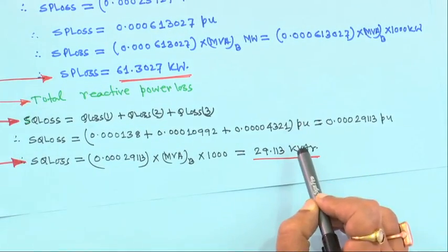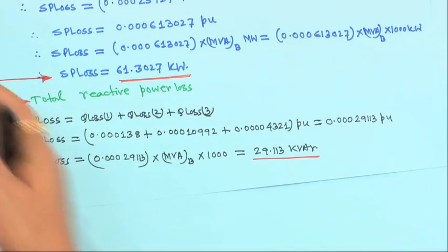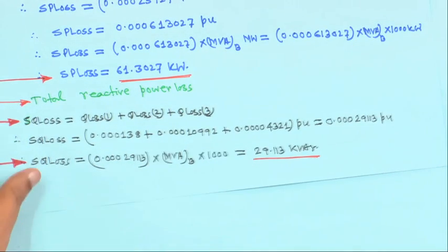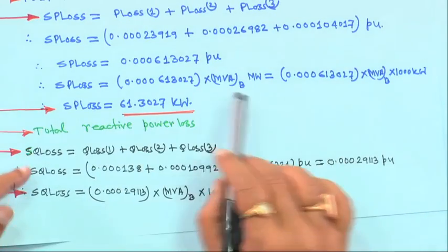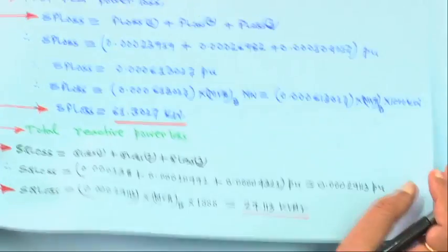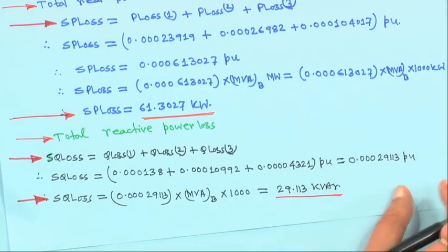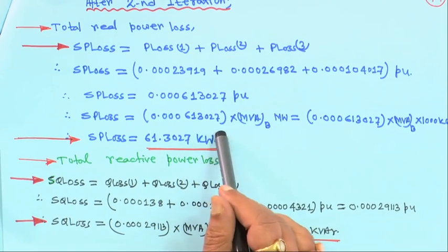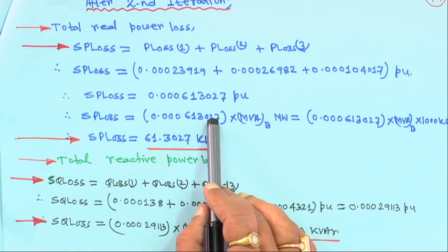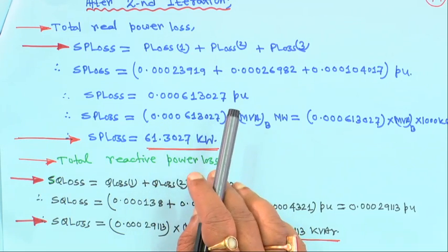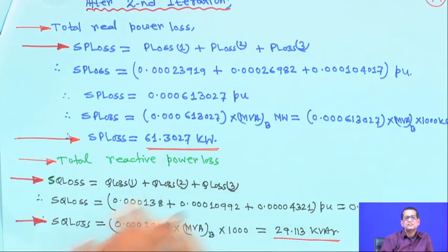If you look at the voltage magnitudes of both methods, you will find that for this example the second method is converging faster than the first one. One advantage of this second method is that throughout this computation there is no trigonometric term or complex number involved. But in the second method, the expression for angle delta can also be obtained using the same initial relationship, the two equations we wrote.